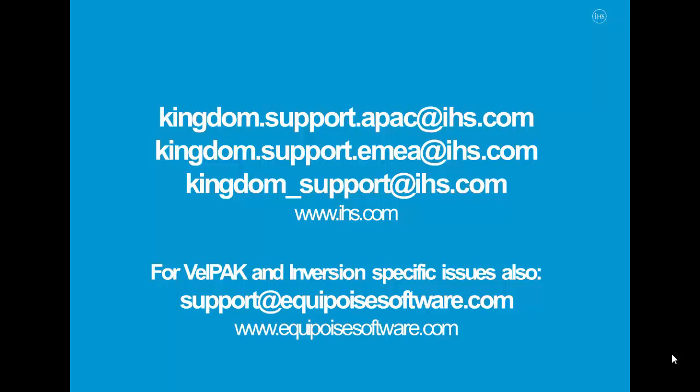All you have to do is specify the model number at the top of the workflow window and then simply run the workflow. The software knows only one realization is required, so it doesn't start looping, and after completion the model is set to that realization. There are handy shortcuts to generate the P90, P50 and P10 models in addition to the best technical case, so you can reset the model back to your deterministic depth conversion very quickly.